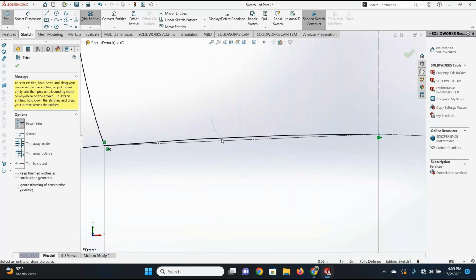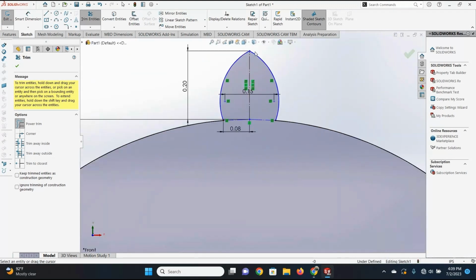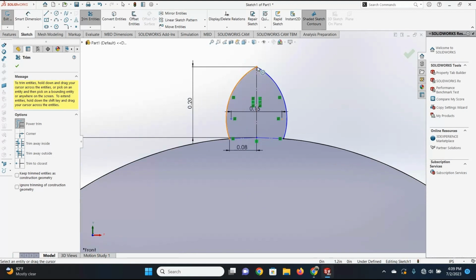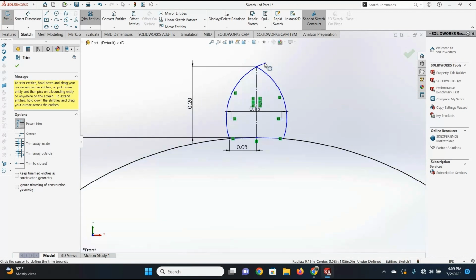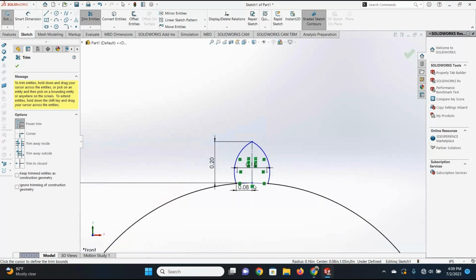And this right here will delete that curved part. Now you see here, this is now undefined, and that is due to the curved part being missing, so the sketch can simply move around, such as that. To redo that, we can just re-intersect them.